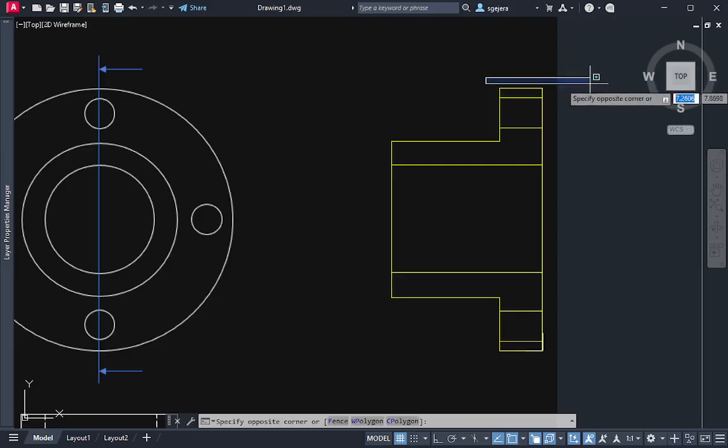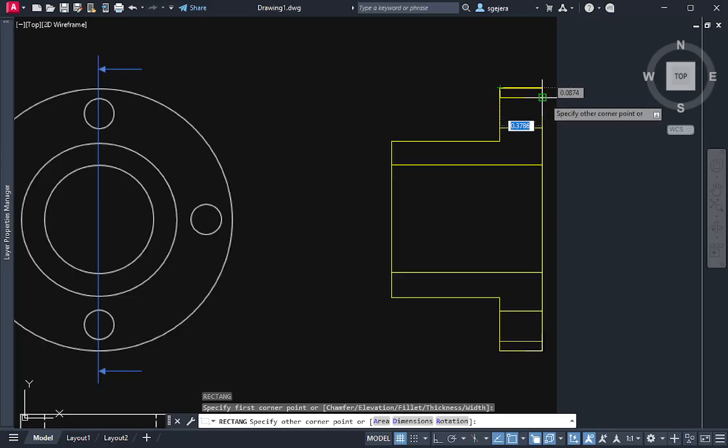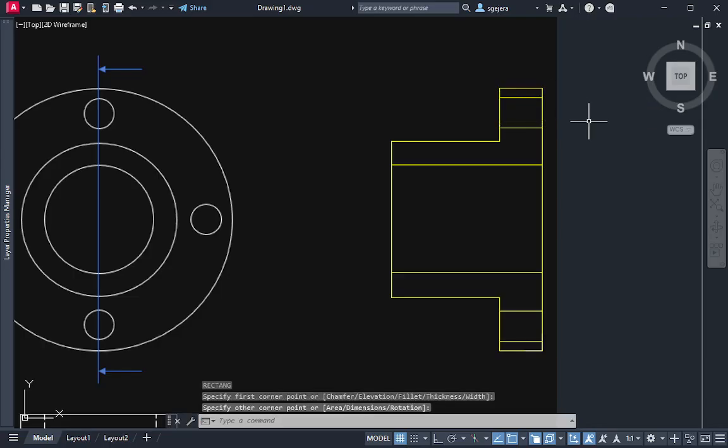So, for the two rectangles dito sa dulo, ito, pwedeng REC lang yung gagawin natin. So, we can do REC and we just papatong lang natin kumbaga. Okay? So, another option is to i-join yung lines, pero that will become harder because some of the lines are shared, no? So, kunwari, itong full length ng line na to is shared by this rectangle and also this figure, no? So, it can be confusing kasi magbe-break at point pa tayo, then join later on. Better na lang na i-overlay na lang natin yung lines natin.